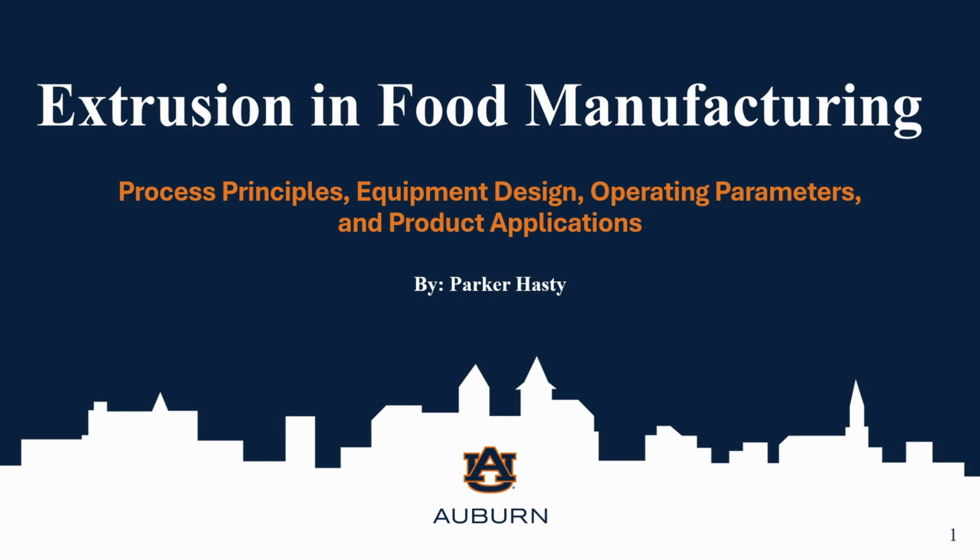Even though this course primarily focuses on manufacturing of polymeric structures, extrusion is also a major process in food manufacturing. Many of the same engineering ideas still apply, including material transport, heat transfer, screw design, pressure buildup, and die shaping. So today I'll walk you through how extrusion works in food systems, the main components involved, the variables that control product quality, and how the process is used across modern food production.